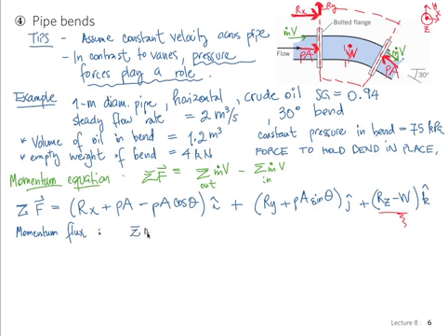The sum of momentum going out, we have two components. So basically, we can separate it in vector form. We're going to write it as m dot v cosine theta in the x direction minus m dot v sine theta j, since the momentum is going in the minus y direction.